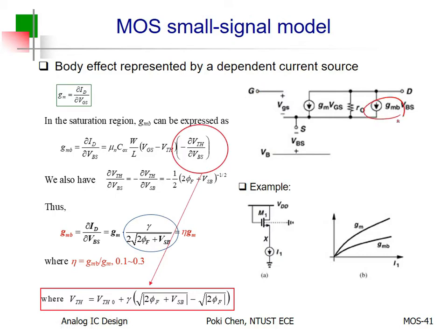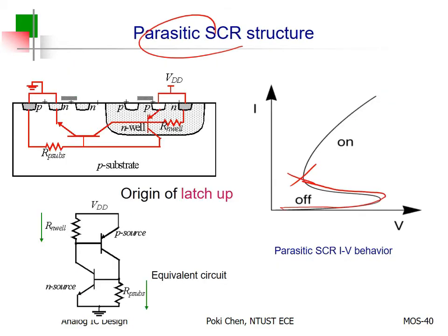to show you this. For microelectronics, you have only this, right? However, for analog IC design, you had better consider your body effect. Unless you promise me you don't have any body effect. For PMOS, it's totally possible. Because PMOS is inside N well, right? So it is inside N well, so you can connect your body contact of the N well to what? To your source. Bingo. That's it. Okay?